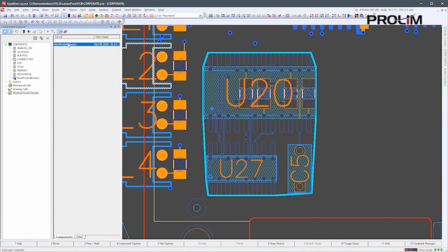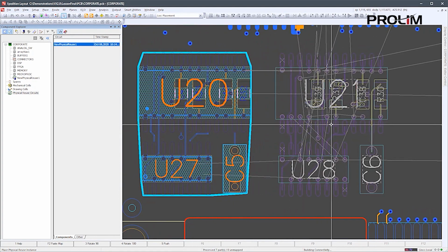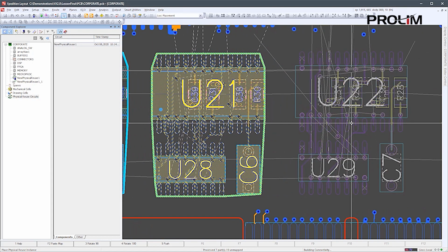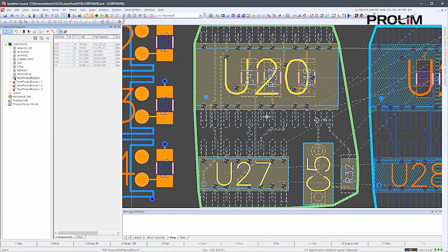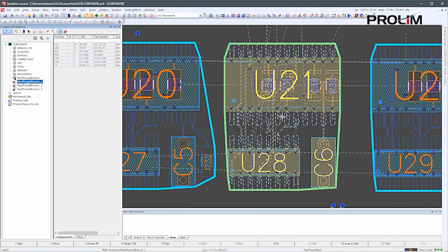In the case of Expedition, reuse modules can even be created and managed similar to single components in a library. This means that not only are reuse modules shared easily, but with this comes the ability to track which reuse modules have been used where, and in case of the need to modify the reuse modules, which may happen if a part is used in the module that is out of stock or has been recently made obsolete.